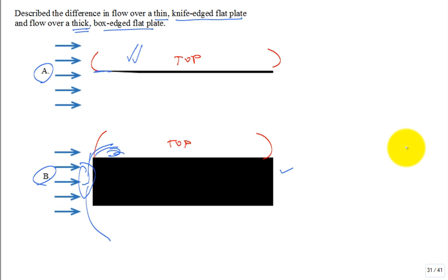There's a lot of trying to divert the flow to get around the cab and then finally skim along the top of that 18-wheeler trailer going down the highway. But we'll use those equations to solve for the drag on the trailer of an 18-wheeler, knowing that there's quite an approximation. Or we have a building sitting in the wind, and the wind is blowing along. We want to know the drag along the side of the building. Well, we'll use the equations, we'll make some predictions, but better put a good 25-50% uncertainty in that engineering calculation because you used equations that were developed for something like this, for something like this.